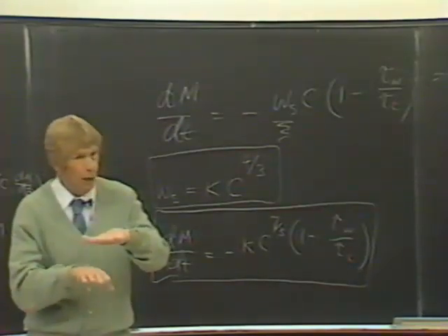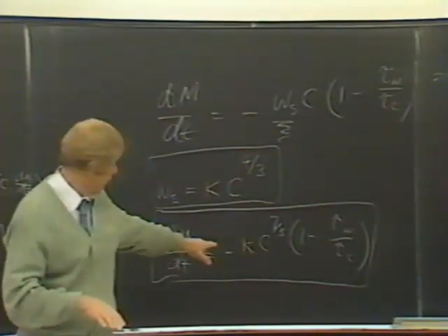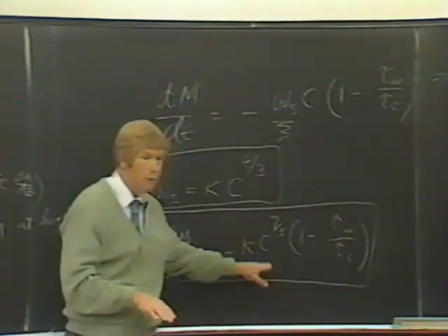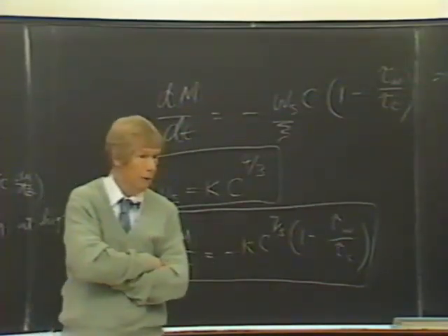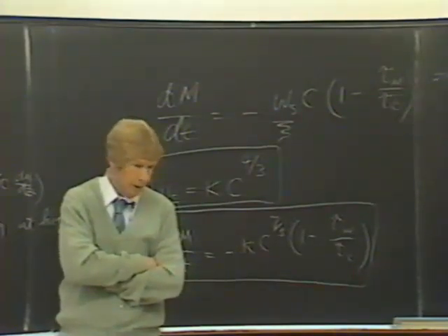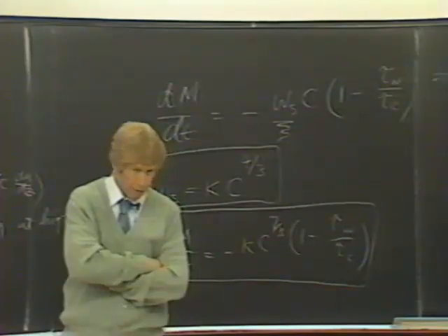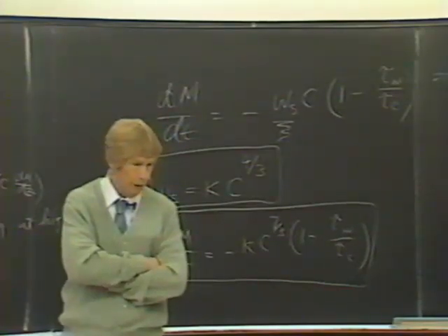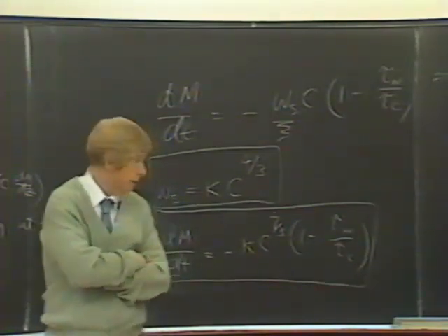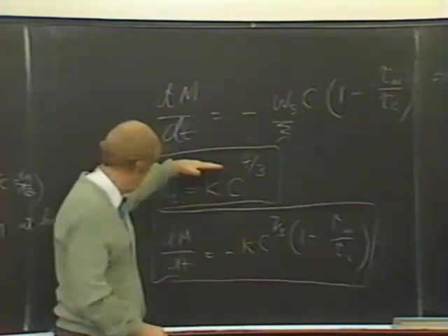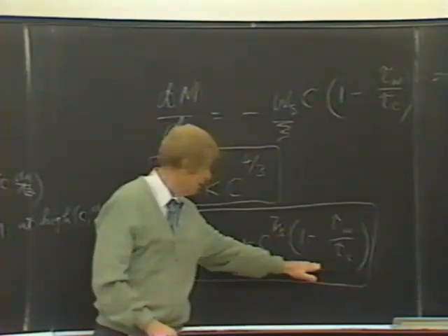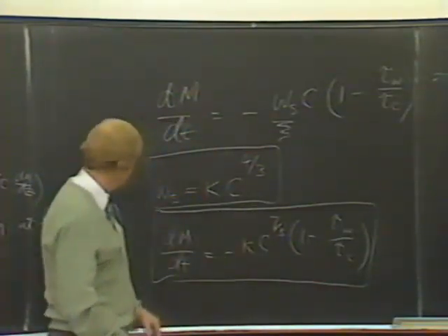The procedure is to lower it to the depths of interest, and it lines itself up with the flow, and water containing suspended particles enters this tube. Then you close it with a spring arrangement and some stoppers. Usually we use toilet cleaner plungers, with a bungee cord between them like this. And close both ends, then raise it to the surface while it's still horizontal. Then on the boat deck, turn it upright and measure the settling velocity of the particles in it.